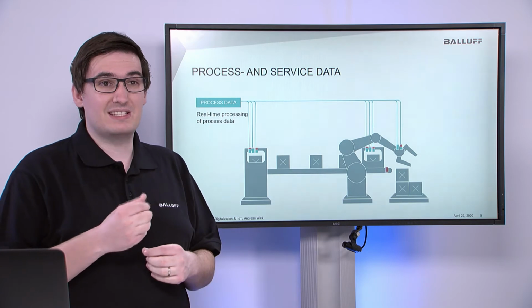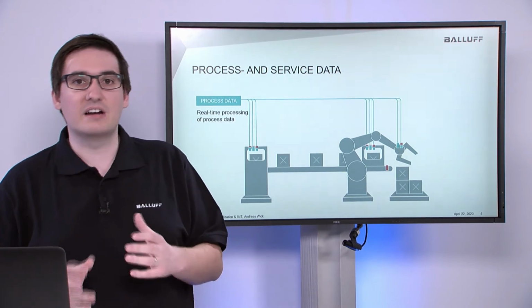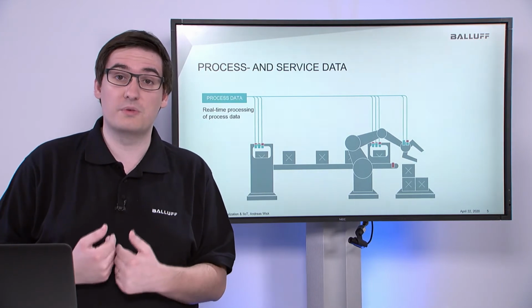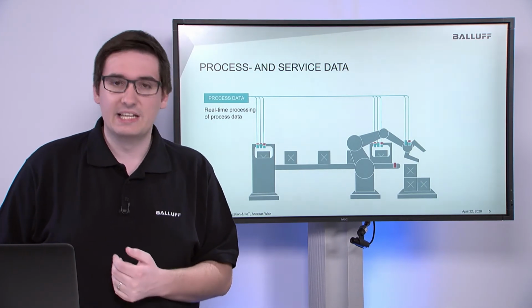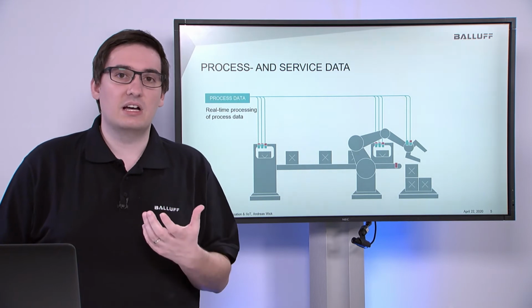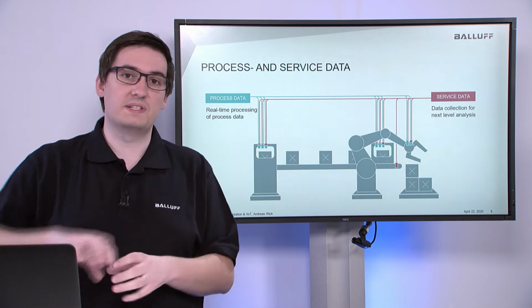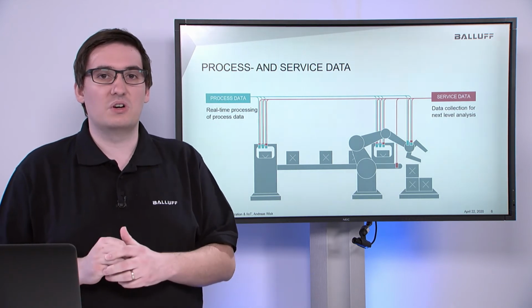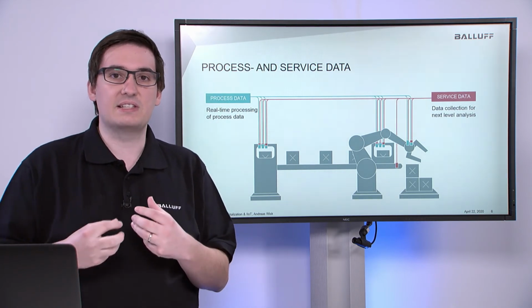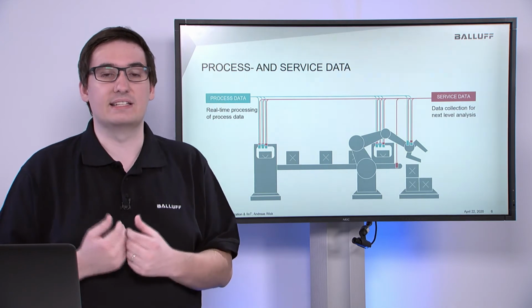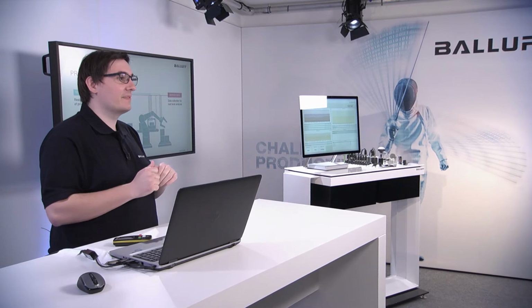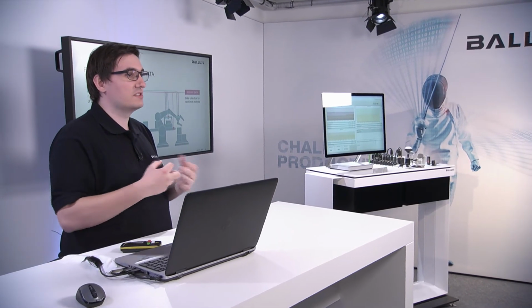But what is a harder task, or not so easy for the programmer to build into a PLC, is handling the analysis of service data, of this additional data. And this is most likely because this data is going to be asked for acyclically, so not on a cyclic basis. And a PLC is not very well suited to do this.